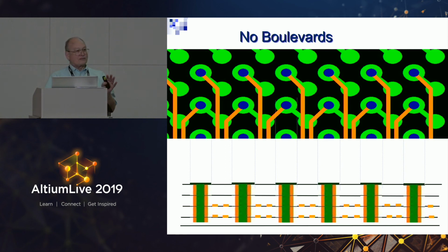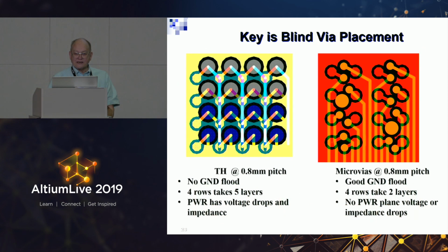If you get rid of 100% of them, that'd be great, because they take up a lot of space. They're the first things to crack for reliability, and they propagate noise all over. And any noise on the power supply, the through holes are going to pick it up and couple it to your traces. And so I'm against through holes now that I've got HDI techniques.